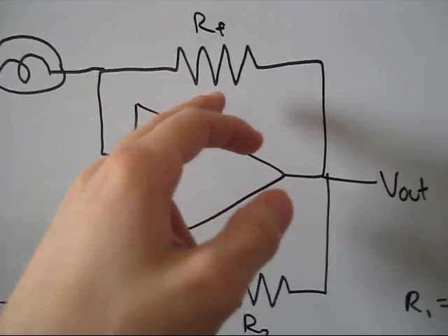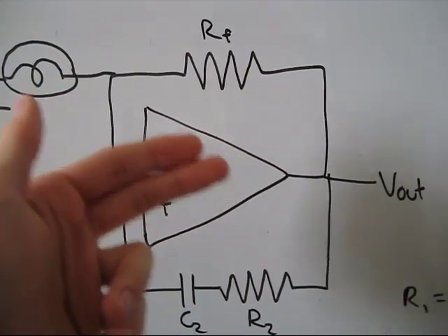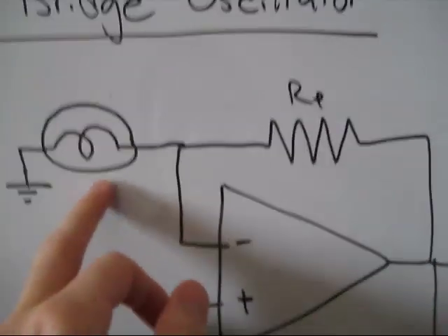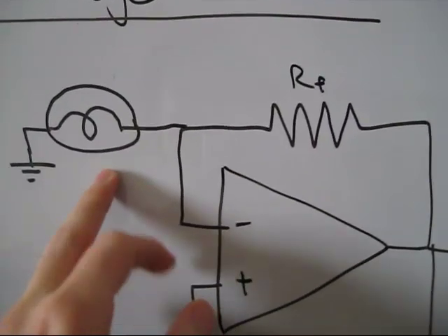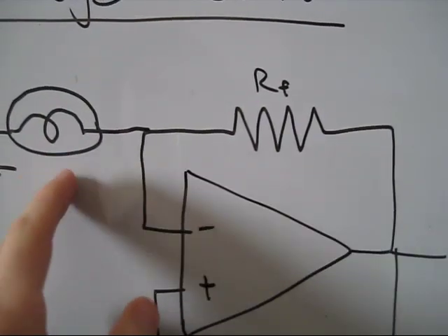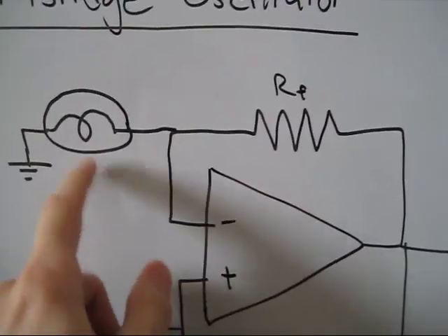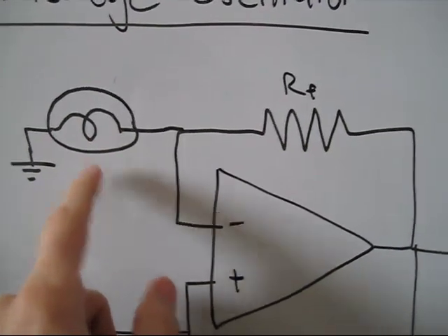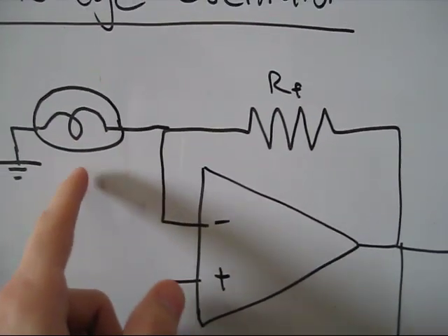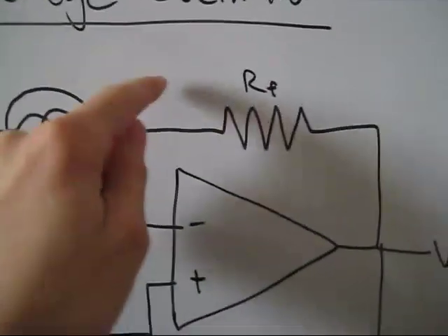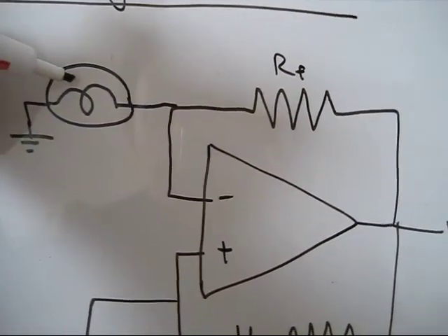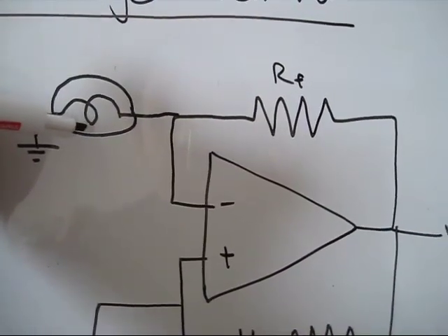So you need to have a little bit of extra gain at the beginning, and then that gain needs to be reduced later on. What Mr. Hewlett actually did a really cool job of is introducing amplitude stability. This was a real lamp, a light bulb, inside his oscillator circuit. And the great thing is that as more current goes through the filament, its resistance increases.